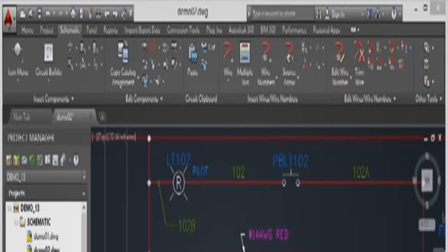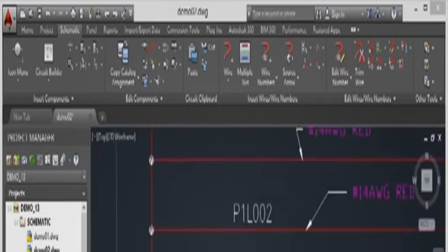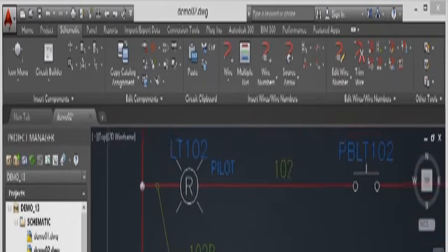I'm going to zoom in a bit more now using the wheel on the mouse, so getting nice and close. We'll select the component, right click, attributes, we'll move that one attribute there, and we'll right click or enter base point, and we'll just move that a little bit over. That looks much neater. Enter to finish, and when I zoom out, that's nicely rotated through the 90 degrees.